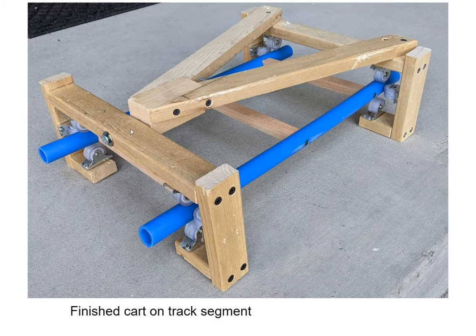This is a two-dimensional coaster, but the front, you can see here, pivots. The reason for that is if you have this pivot, then all 4 wheels will have the same load in them. If you design a cart where all 4 wheels are fixed, 3 points define a plane, and you can't make the track or the cart perfect enough to have even loading on all 4 points. So this bar in the front pivots in a roll degree of freedom, which makes it so the wheels are always evenly loaded. That's better for stress, better for the track, and better for lower friction.